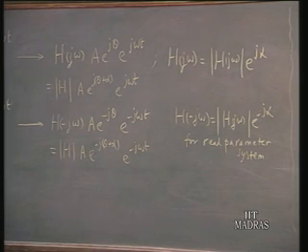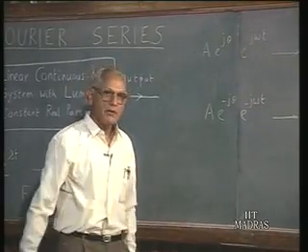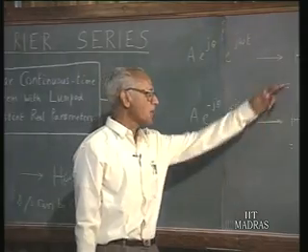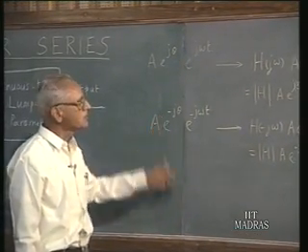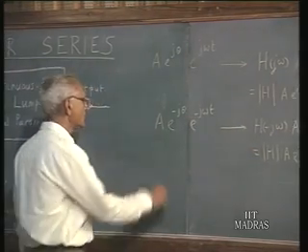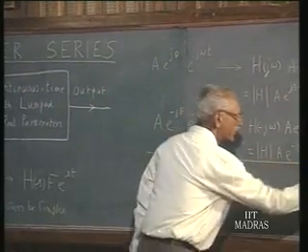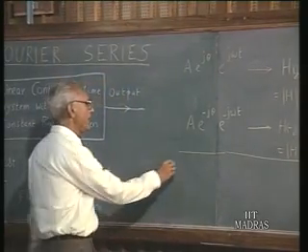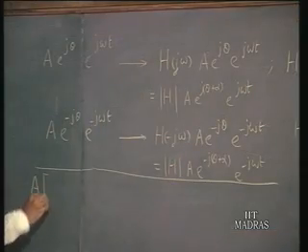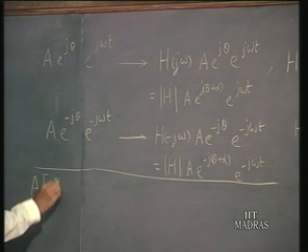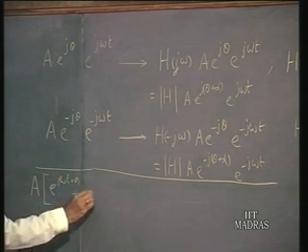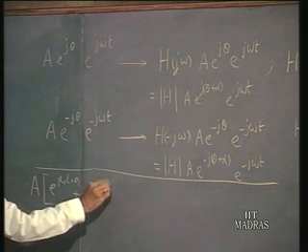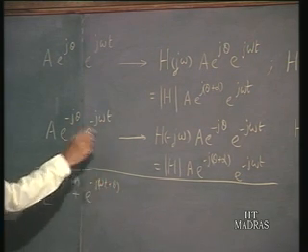Now let me imagine that we have a composite system which is the sum of these two. By virtue of linearity, the responses also can be summed up. So the sum of these two signals will give rise to a response which is equal to the sum of these two. Therefore, if you do that, then you have e to the power of j(ωt plus θ) plus e to the power of j(minus ωt plus θ). After all, that is what we are having here.